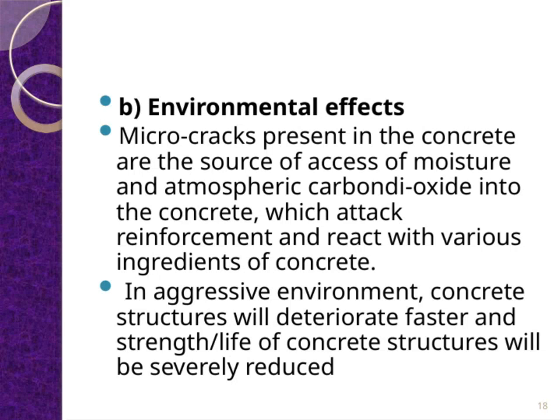Let's talk about the environmental effects on concrete. Microcracks that form within the concrete are more than just tiny imperfections. They actually serve as entry points for moisture and atmospheric carbon dioxide. When these substances penetrate the concrete, they can cause significant damage, especially to the reinforcement steel inside. The moisture facilitates corrosion, and the carbon dioxide reacts with the concrete ingredients, further weakening the structure.